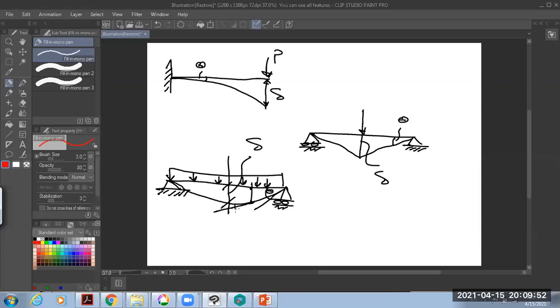But now, what is the slope at this point? The slope at the mid of the span is always parallel to the beam itself. That means the slope is equal to 0 here. The mid-span slope is equal to 0. And this is one question from our exams. Okay, very good. What else do we have to know about cantilevers and beams? Let us see our slides.